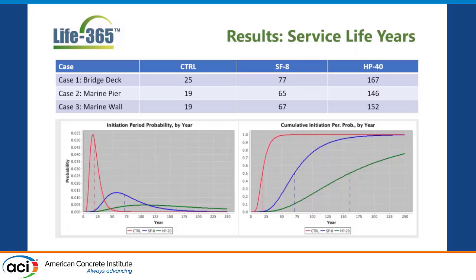Sounds a little confusing, but it's a probability curve. CDF. This is saying that at 90% confidence, the service life is 125 years, and 10% is greater. So the silica fume is pretty good in that.